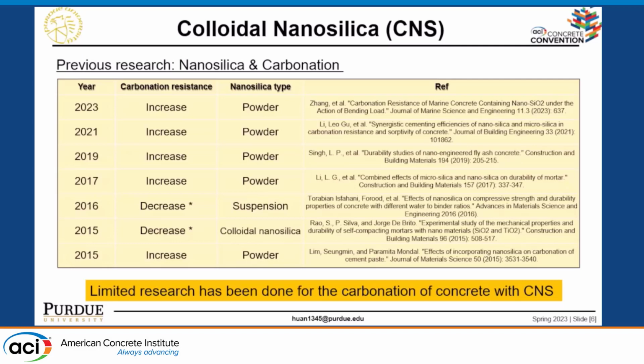Regarding the carbonation of nanosilica, we did a literature review, and this table shows part of the papers that we reviewed. A lot of studies have been done, and we found that most of them use powder form nanosilica, and the result indicates an increase in carbonation resistance, that means less carbonation absorption.